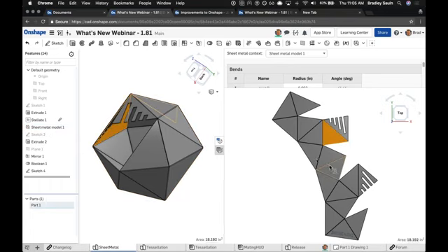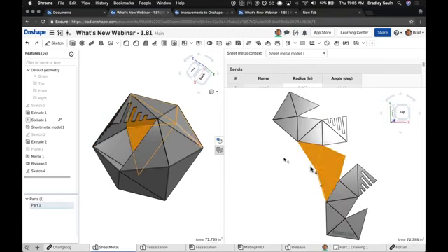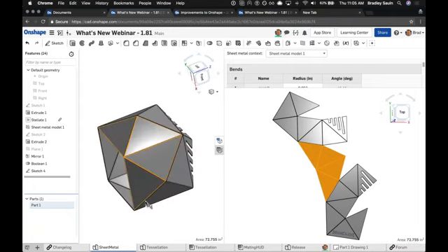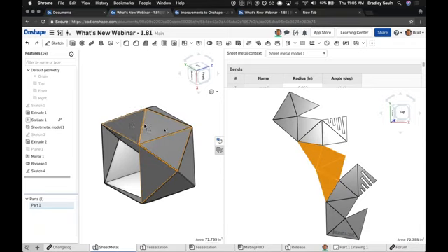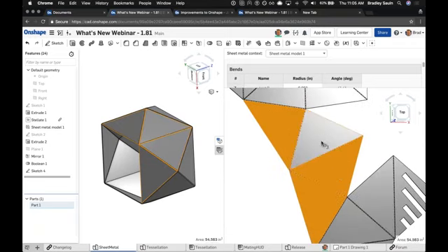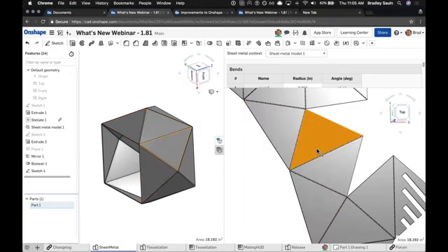But now as well here, I have some flat pattern grille pieces I want to cut. As I highlight the components I'm focused on, I'll see they're centered around the back side of this component. So I want a nice, symmetric, even grille cut across this entire board. I can come in here, click on any face in the flat pattern, and do my same sketching workflow.